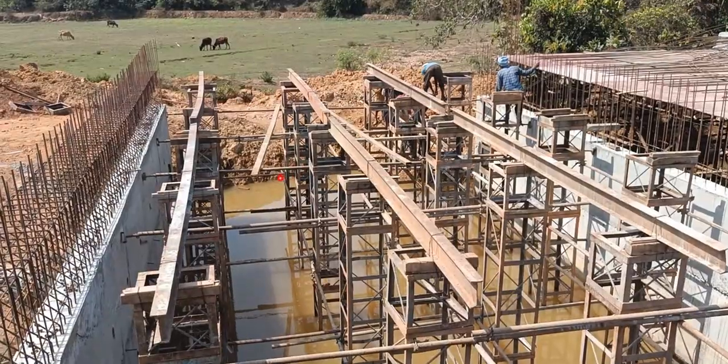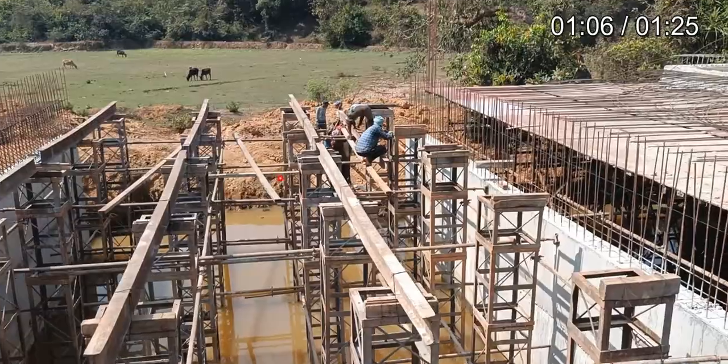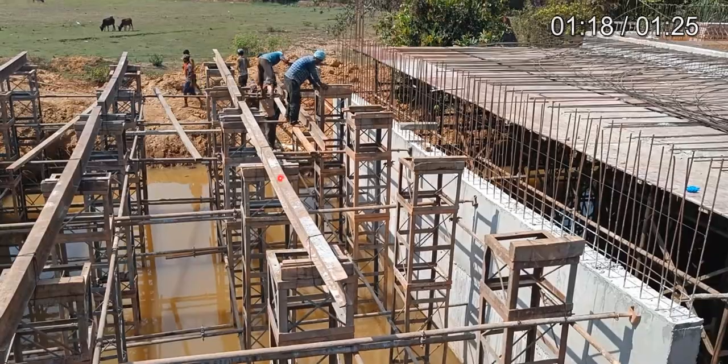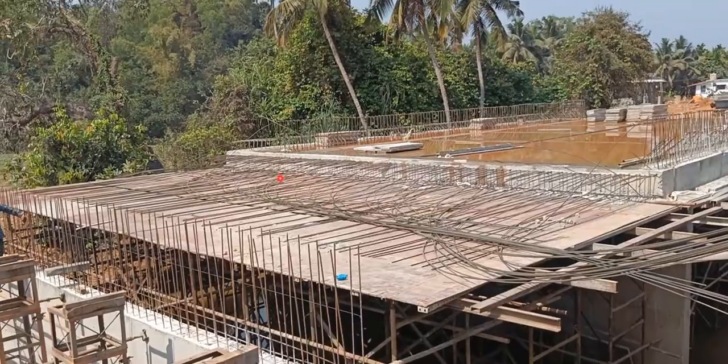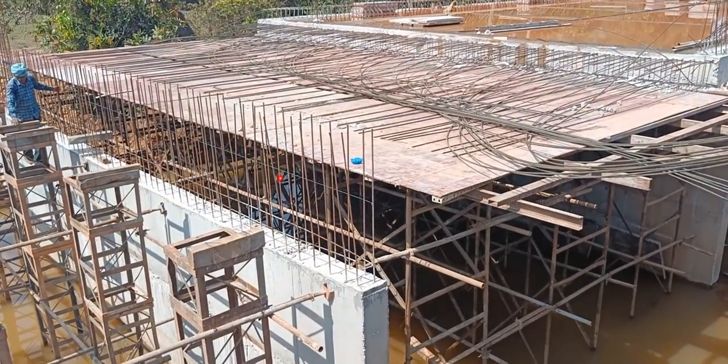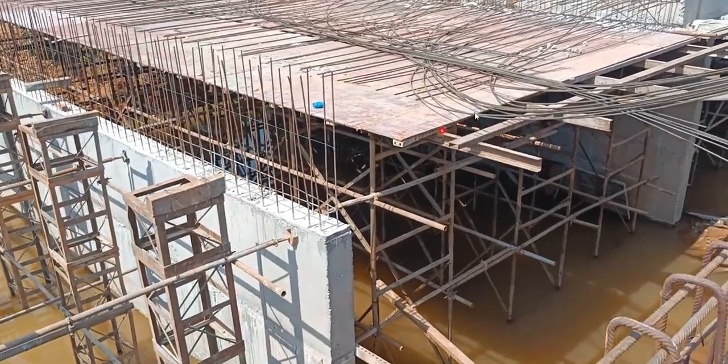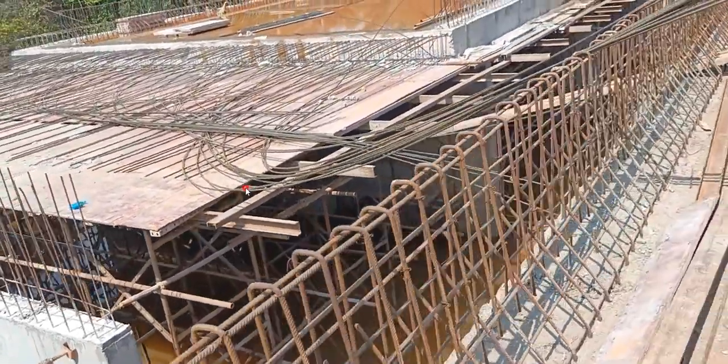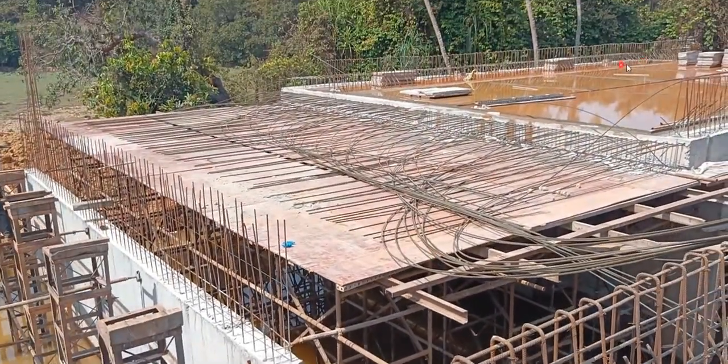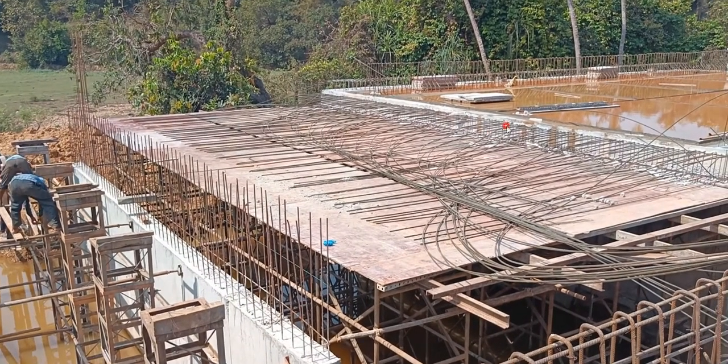Okay, so in this way they are going to keep it, each and everything, which we already did in the deck slab, the previous slab what I told you, the same thing. Then they have put up this centering here. Okay, sheets they have put up, and already this particular slab was casted. When this slab was casted, we have left certain bar, it is called as double bar. Now here whatever reinforcement I'm going to put, that same will be continued here also.